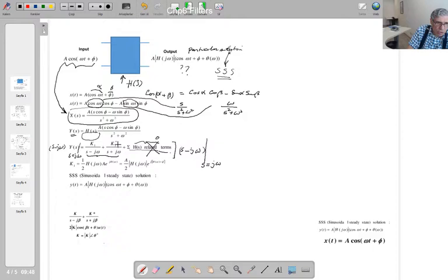For this case also it's going to be 0, isn't it? You are multiplying this with S minus j omega and replace S with j omega, so this is going to disappear as well. So if you do this multiplication for the first time, this S minus j omega and this S minus j omega disappeared. What is left on the right hand side is just K1. So I am trying to calculate this K1. So K1 we found on the right hand side of this equation.